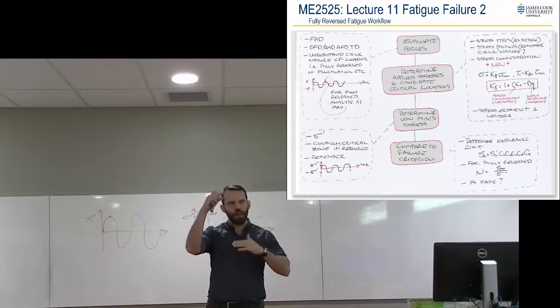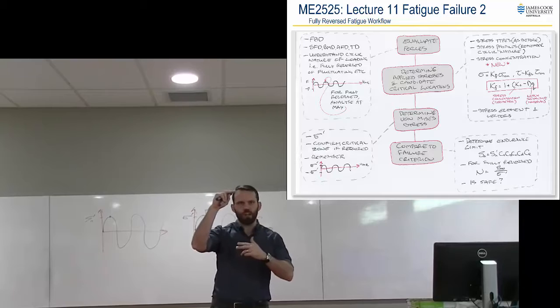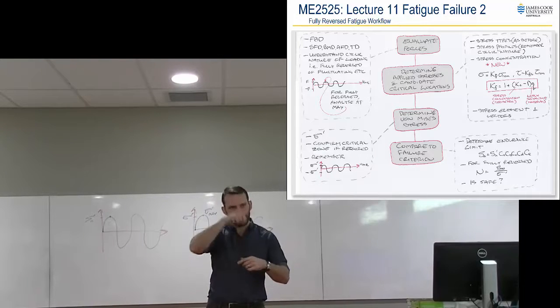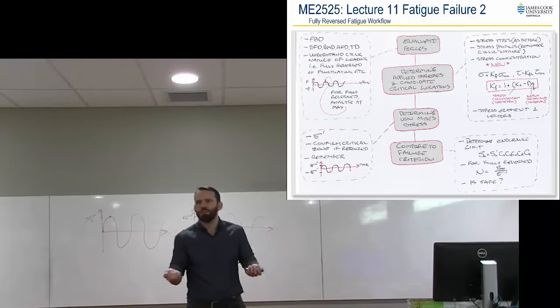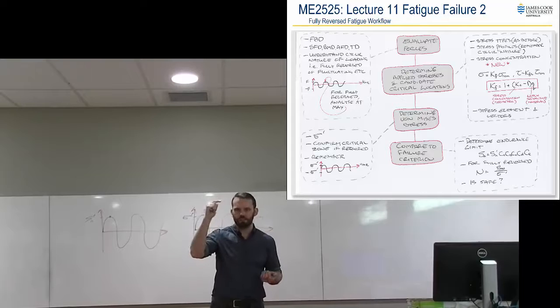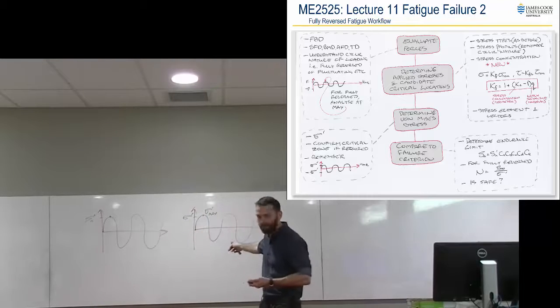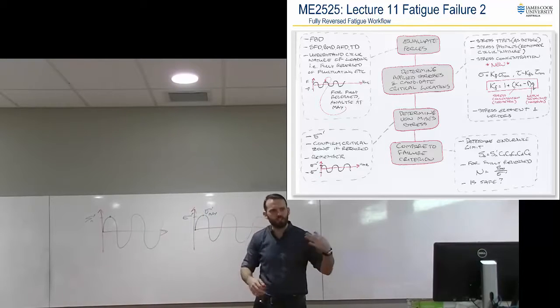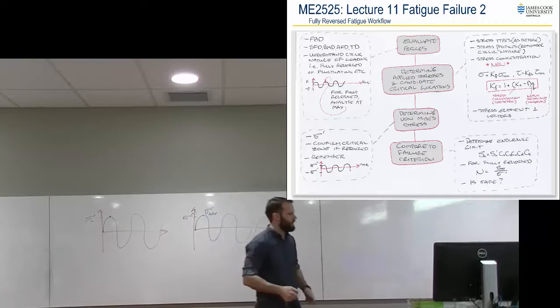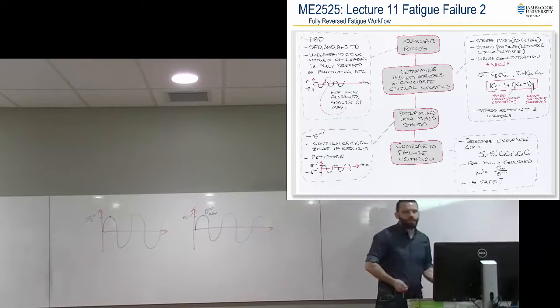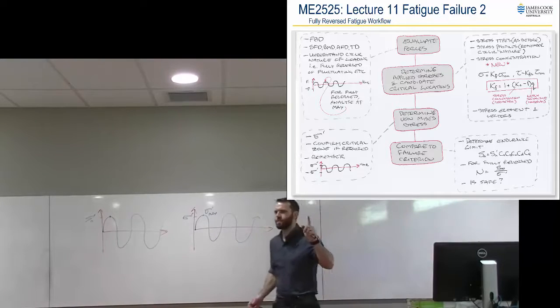So remember, our bending is maximum in top and bottom, but if that shaft's spinning around, then that's actually spinning around on the shaft as well with it. So just keep in mind that. But when we're talking about bending, we're analysing a single point and then assuming that that single point is cycling like this, so then that's okay. But just at this point, I've just put there, just remember that it's cycling just in case something funny is going on. And then we apply stress concentration, and this is one change for this year.